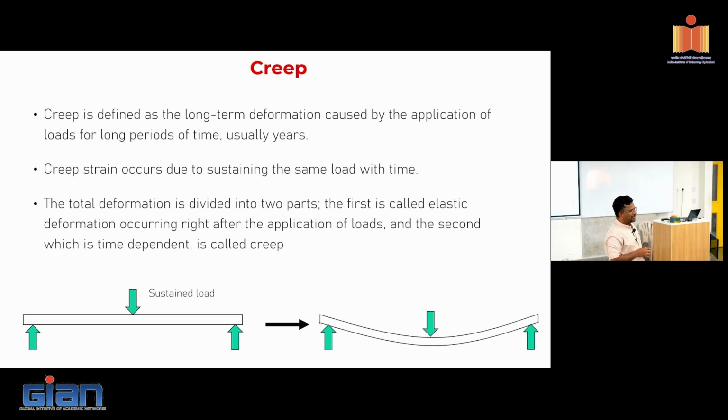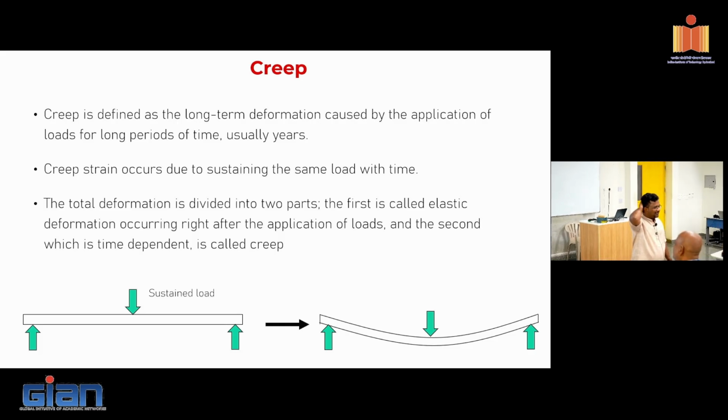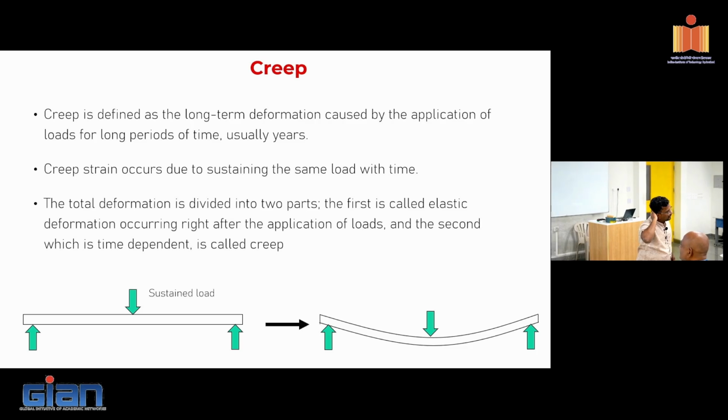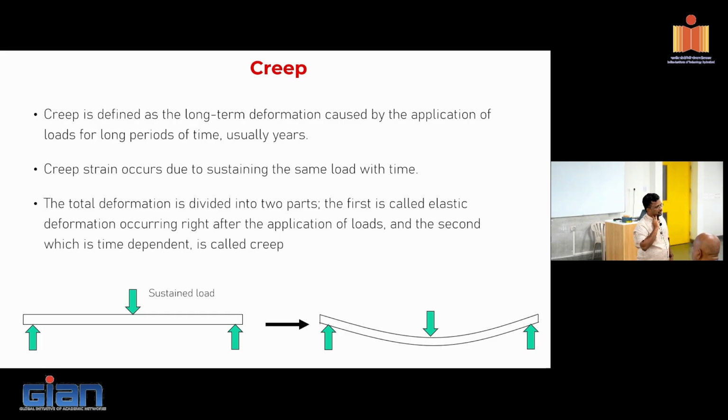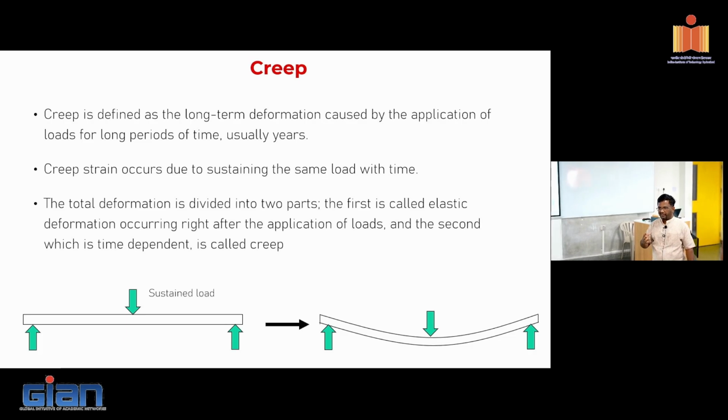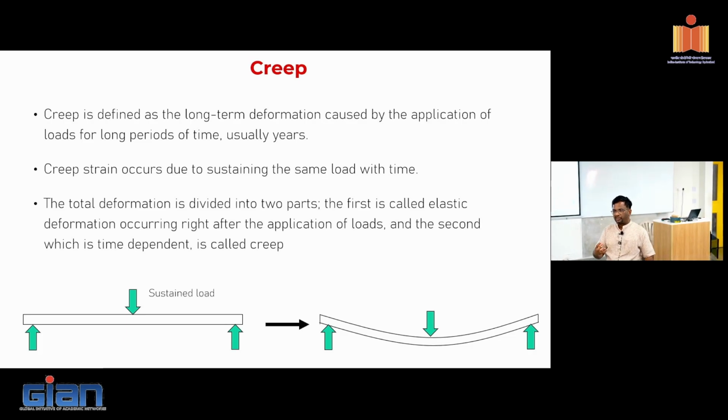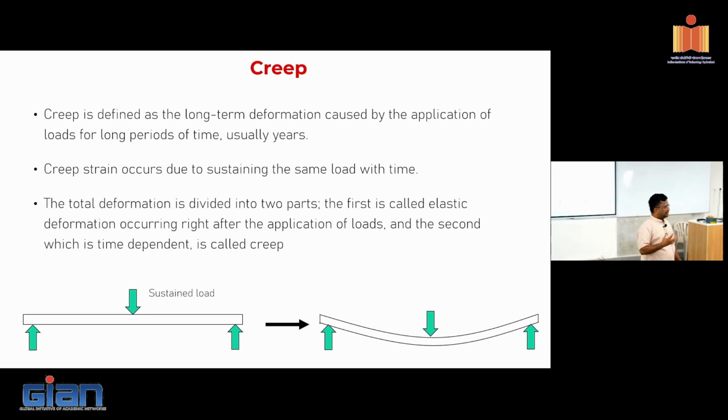Calcium hydroxide? No, calcium hydroxide converts itself to additional CSH, it's better, no? The calcium silicate units, their adjustment will take place under sustained load. Why does that adjustment happen? So what we are saying is that there is some softness happening in the material, or in other words, the elastic modulus of the material reduces.